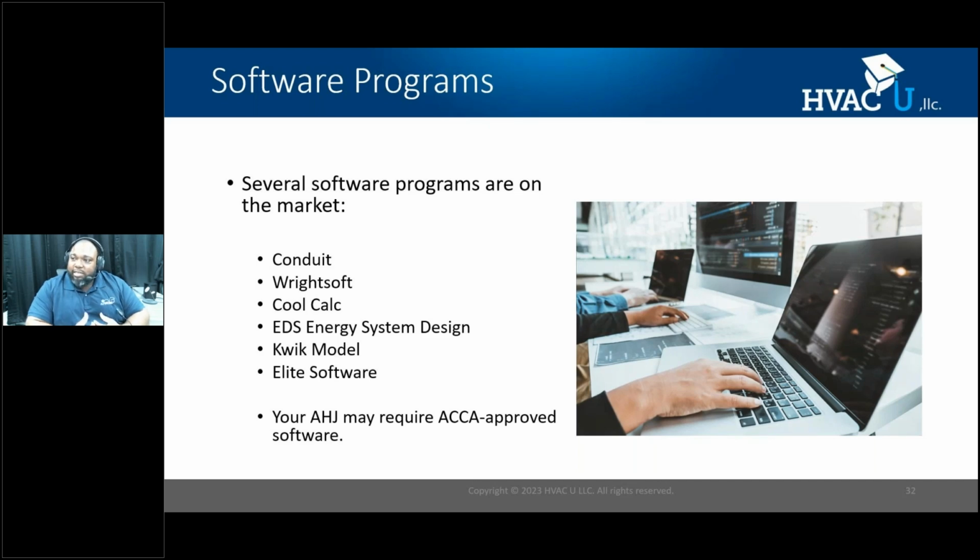My take is if you live in an area where that's not the case, doing a load calc is going to do you justice on that customer. When we talk about an ACCA approved, they have certain design criteria that you have to meet when you size that equipment. So just take that into account. Each and every location is different.